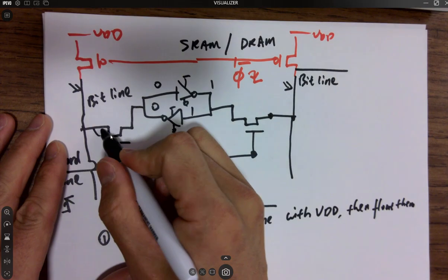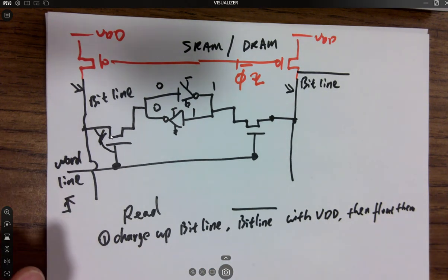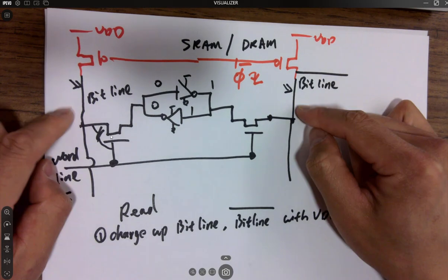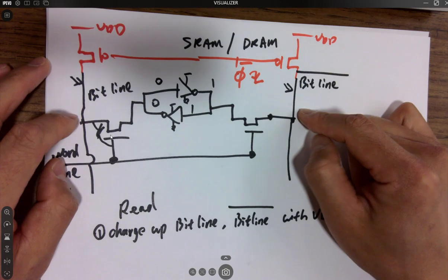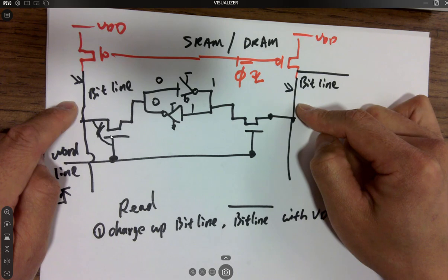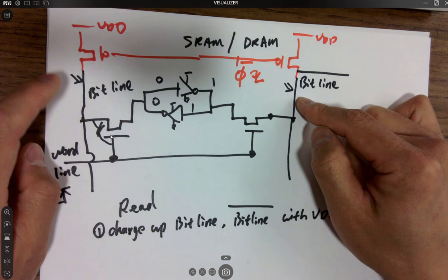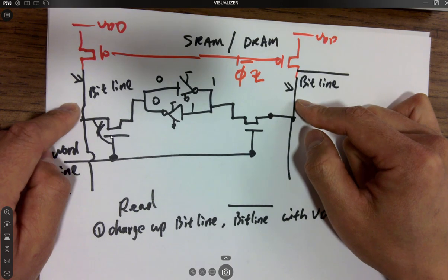Capacitors. So there are capacitors in the gate, right? There are some capacitors over there. So the line is going to store what? It's going to store a VDD. So pre-charge these two lines with VDD first, okay? And then shut it off. So whatever is being stored on the line is called what? It's floating VDD, right? It's a floating VDD. It's not permanent. It holds a finite amount of charge, and the voltage is VDD, and that charge will give you a VDD if you probe it against the ground.